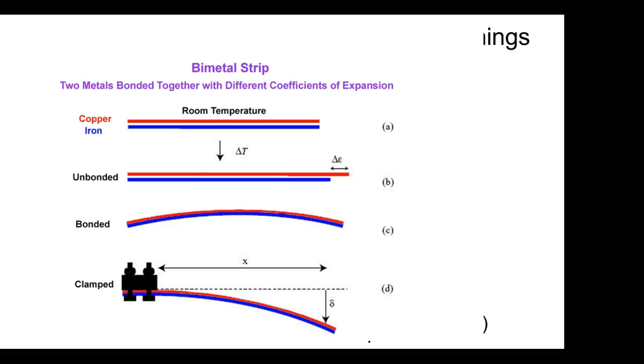Go down to Lowe's and look up a 15 amp, 125 volt fuse, and look at a 15 amp circuit breaker. You're going from cents to dollars, right? You understand that? So that's a big advantage of fuses. And this is why in industry you still have a lot of fuses, especially on motor circuits and stuff like that.